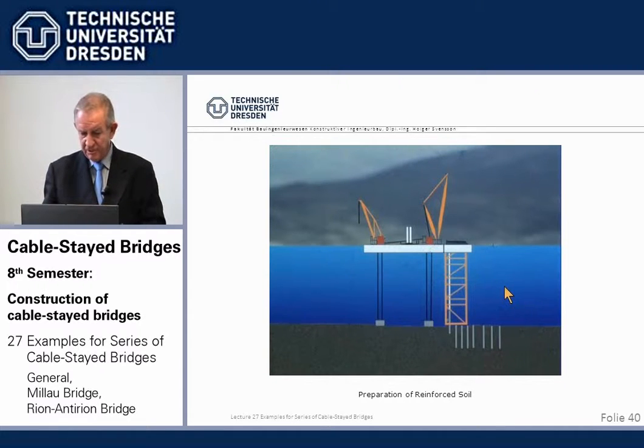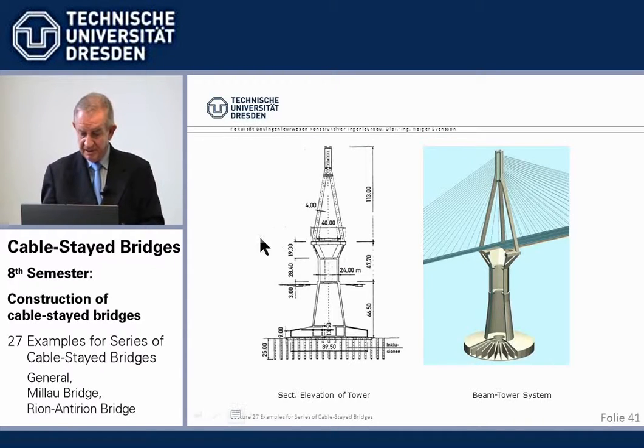Production was also thought out quite nicely. We have here a floating barge with all the driving equipment and so on anchored to concrete blocks at the bottom. And then, first of all, these steel piles are hammered in. The mud has been taken away before. And then we have here this layer of gravel and tower foundation hollow up to here, and then we have the 4 tower legs. I've told you that.